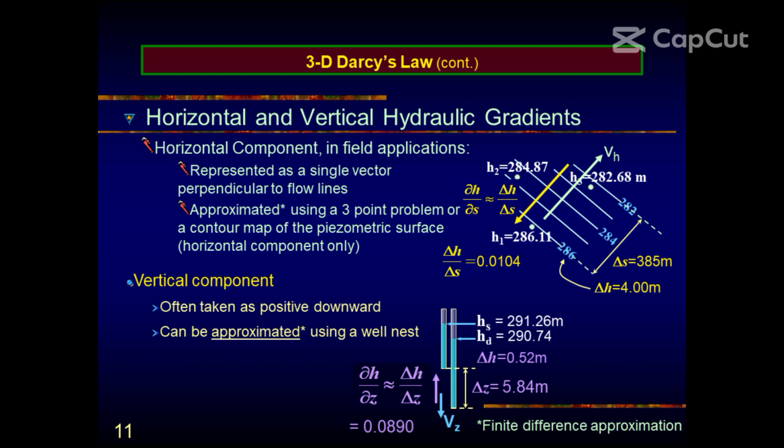Although it is almost saturated, the pressure is below atmospheric. For that reason, you have the level in the well to be lower. Although the water table could represent the capillary fringe, because I said it's almost saturated, isn't it? But when you dig a well, instead of the level to be the same as the level of the water table, no, because of the capillary fringe.